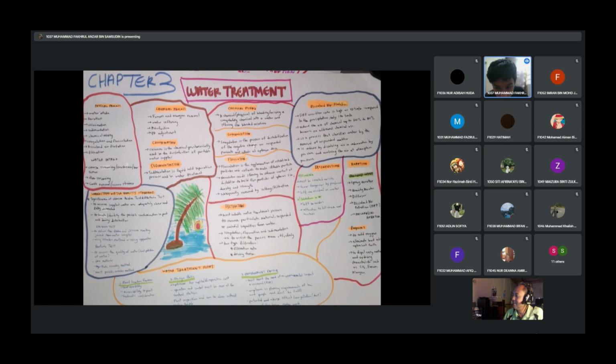Today is water treatment. First is the physical process: water intake, aeration, chlorination, sedimentation, chemical mixing, coagulation, and flotation, air flotation, filtration. Water intake includes coarse screening, trash rack and bar screen, and fine screening.